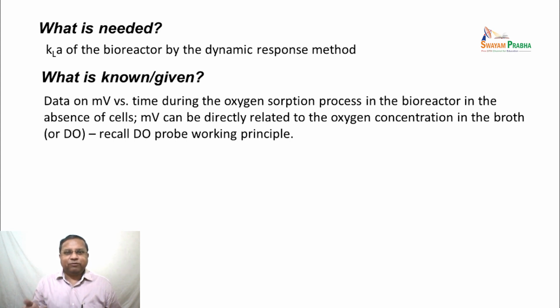These have to be in an electrolyte for an electrochemical system. The electrolyte happens to be KCl. These are placed in a housing which is dipped into the broth in which the dissolved oxygen level needs to be measured, and this housing is covered with an oxygen permeable membrane.